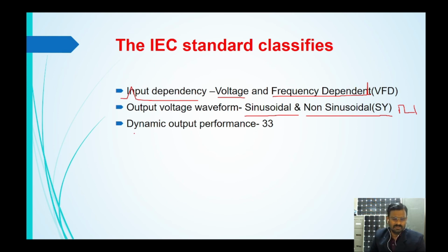And dynamic output performance: during the changeover time, it is going to provide a 100 millisecond delay, with up to 10 milliseconds interruption time, and 20 milliseconds for voltage regulation to settle down.